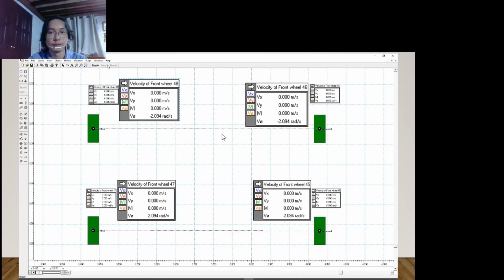Each wheel is connected to a sprocket and a DC motor via a shaft. So the ratio of the sprocket will be 1:1, so that both the wheels will turn synchronously at the same speed. The turning speed to steer the wheels is 2.09 rad per second, and it is using a DC motor with the speed of 20 RPM. Also, they can turn clockwise and anti-clockwise according to which direction the wheelchair is supposed to go.